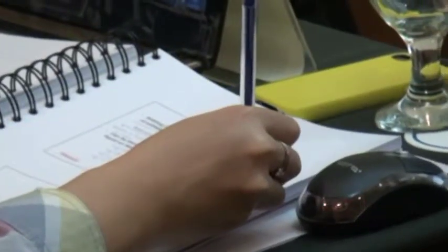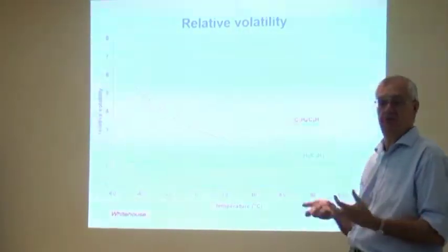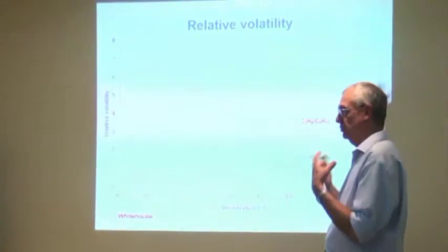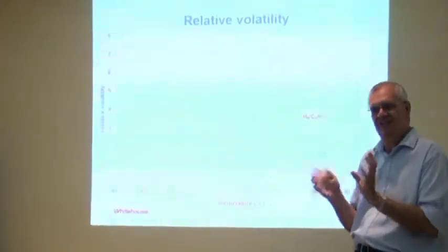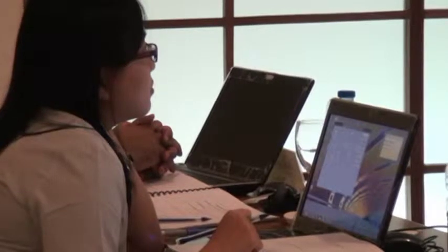You might infer from this that we should always operate our distillation columns at the lowest possible pressure. That makes the components easier to separate. Now that's true apart from the always bit. Okay, sometimes you have to change the pressure for other reasons, but directionally, reducing the column pressure helps. A column probably has 8 or 10 components in the feed.